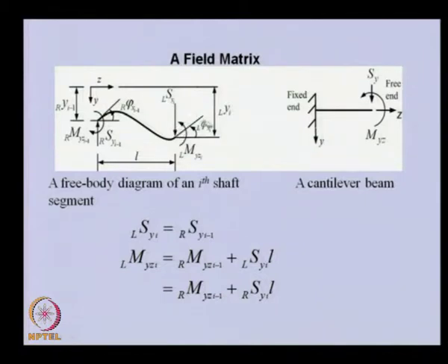So, all the variables like linear displacement will have y I left of I. L represents that this displacement is left of the ith disk, and this is the angular displacement, the slope. Basically, if we want to see the ith shaft, this is the ith shaft. Here we have the ith disk and here we have the I minus 1th disk.